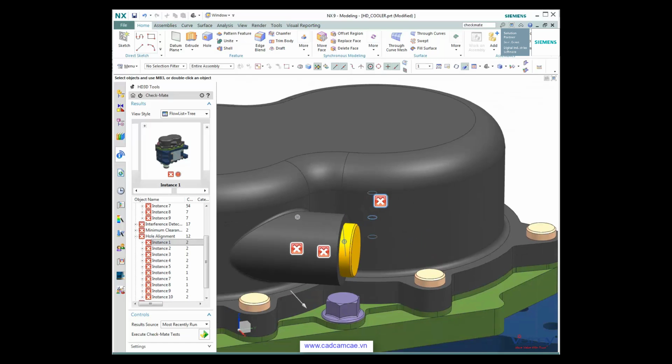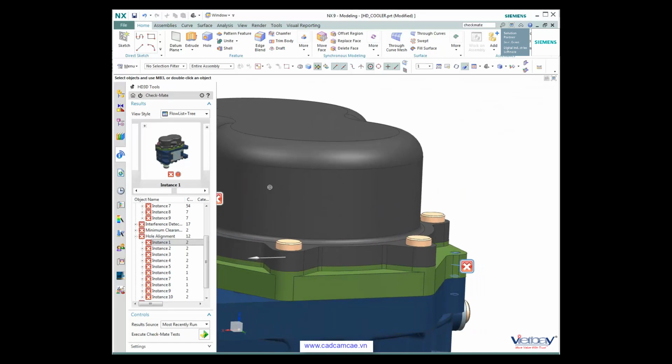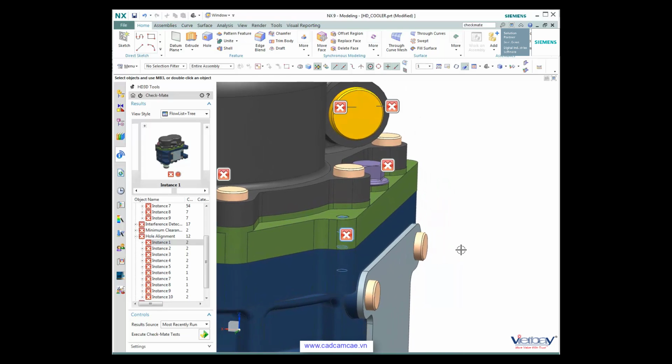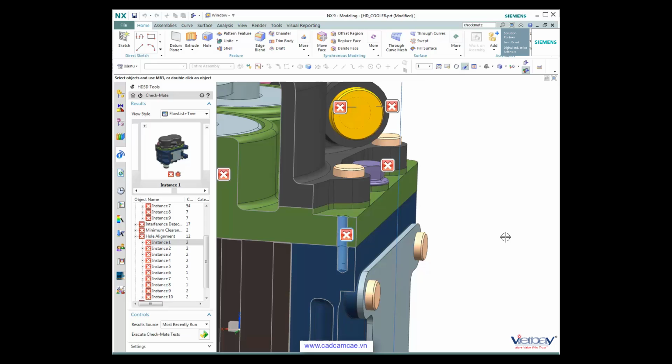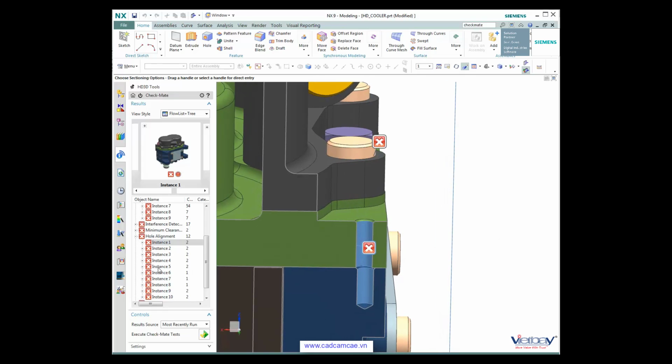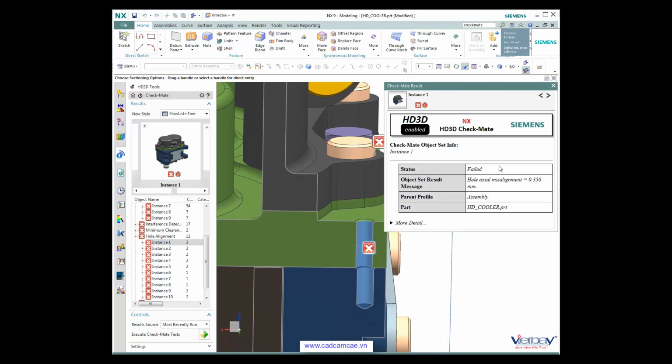Let's take a look at a hole alignment rule violation. The holes on these two components are not lined up correctly. Minor misalignment of holes will result in issues related to joining. Fasteners may not fit correctly. Again, this is usually not found until assembly or out on the shop floor.